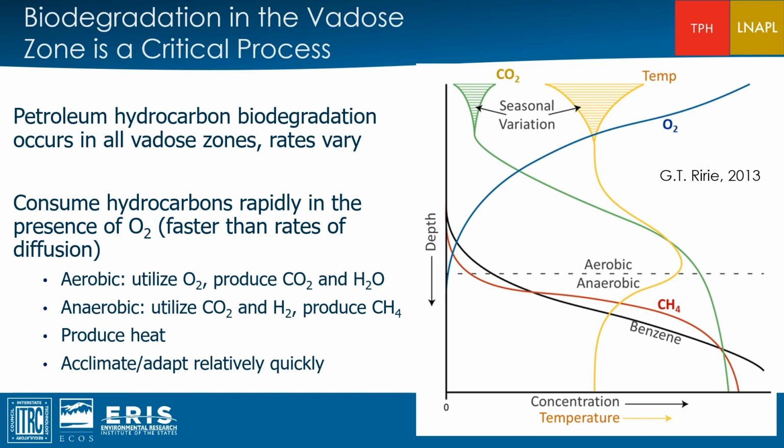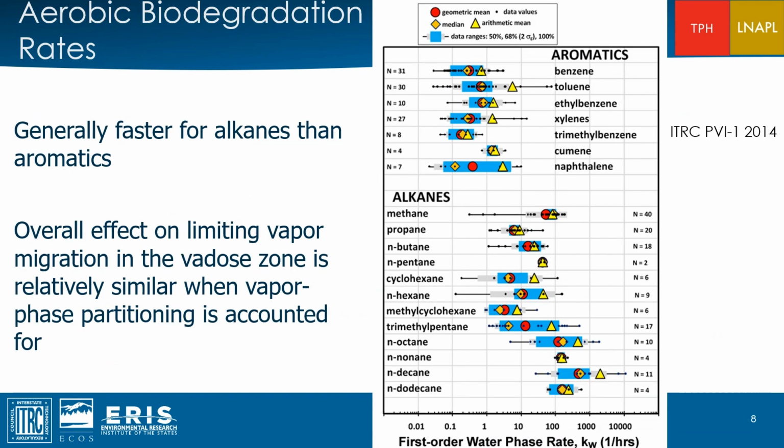It's also important to point out that the figure shown here is generally a representation of the conditions found in the vadose zone above an LNAPL source, and the conceptual model provides the theory to support soil gas and temperature methods for natural source zone depletion. The aerobic-anaerobic interface would be located much closer to a dissolved phase source, and there would be little, if any, methane generation. The biodegradation of petroleum hydrocarbons will occur in virtually all subsurface environments.